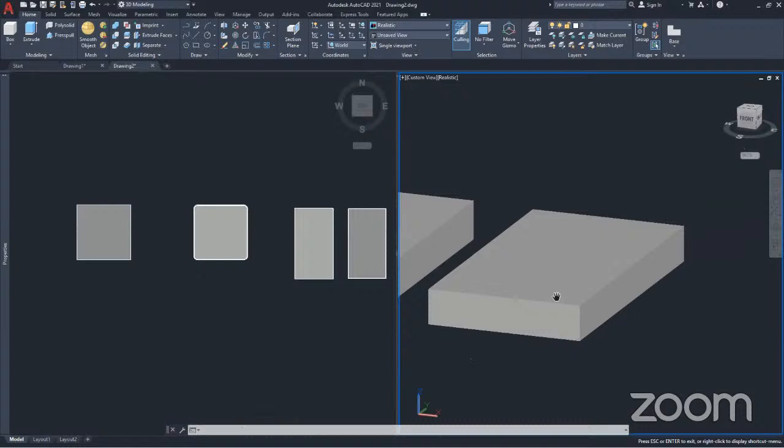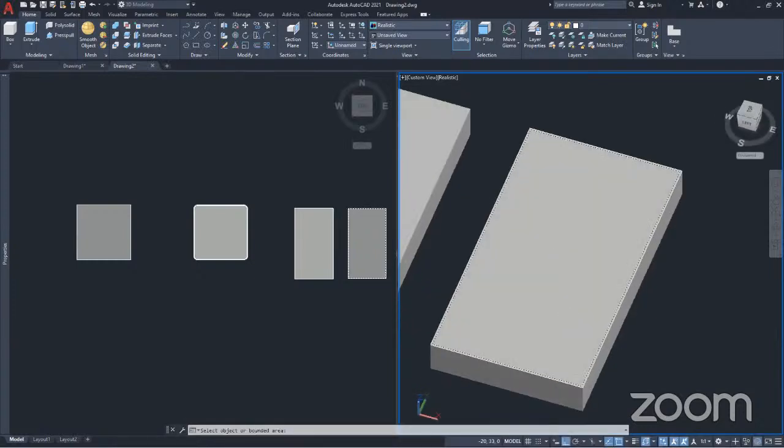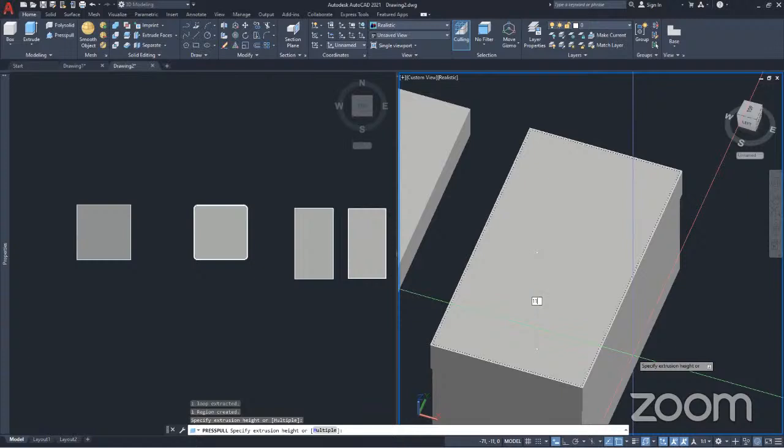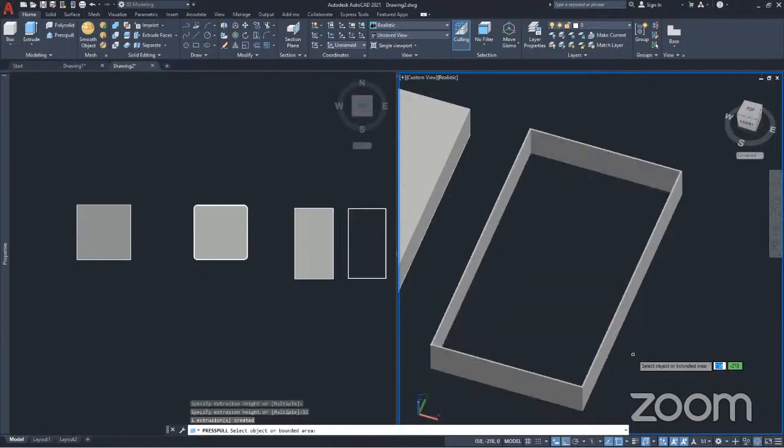So let's do that. I'm going to use the press pull command. I'll select this face. Let me orbit so you see it clearly what I'm doing. I'll select this face and then press pull inside by 11. Let's see if that works. Oh, okay, 11 takes it out completely.